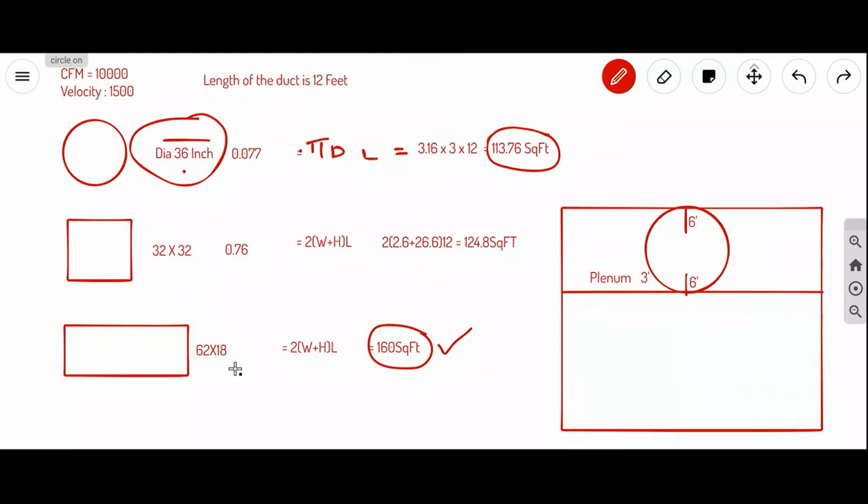It is possible only for this duct, right? Got it. All MEP services. Yeah. So now if I take this duct, how much loss is happening? See where 113 is and where 160 is. So to make 160 square feet, think 160 divided by 32. How many sheets are required? 8 by 4 sheets, no, sir? 8 by 4 sheet, 32 means 5.5, around 6 sheets. 6 sheets are needed. And here, 32 means around 4. So there is a lot of difference, right?